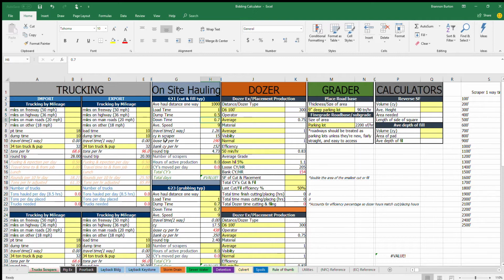And then we put on average about 0.7 minutes for when they get stuck behind multiple scrapers, or a machine breakdown, or a variety of things, like having to get out and look at a cut. Hopefully these are areas where we can reduce waste, but for right now, this is about where we've observed the scrapers and what they've been able to do.